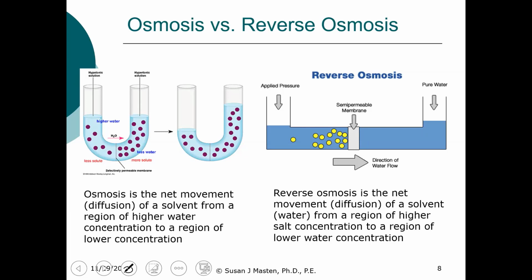So looking at reverse osmosis, we need to talk about osmosis. When we talk about osmosis, there's a little video experiment that you can watch, but normally what happens is, for instance, here's our membrane right here. And we have on one side of the membrane a less concentrated solution, and on the other side, a more concentrated solution. So what's happened is we have flux of water. The membrane is permeable to water, but impermeable to the salts in these solutions. We'll have flux until the system reaches equilibrium, so until the concentrations are constant.